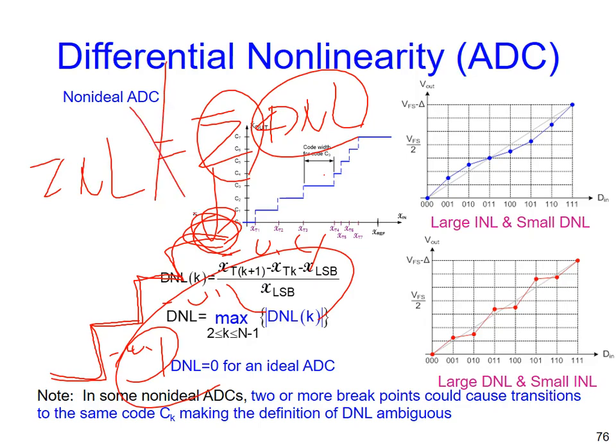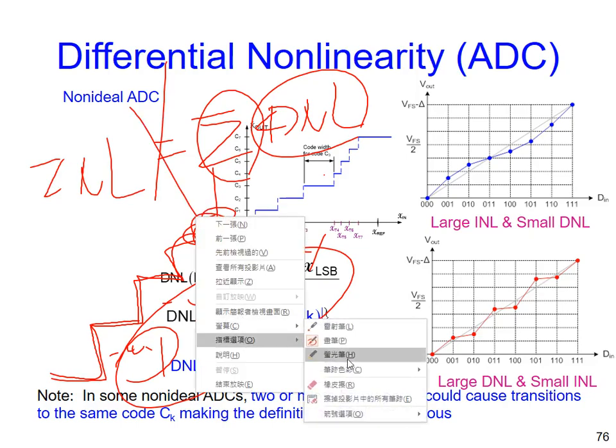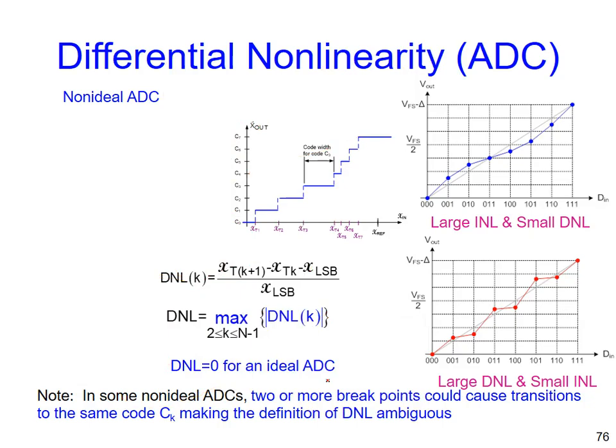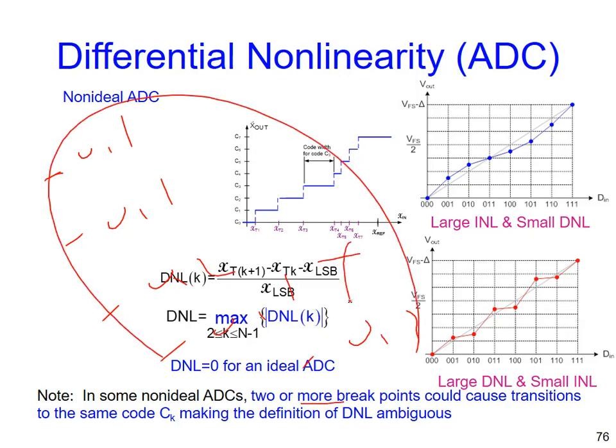Okay, so this is the relationship between INL and DNL. You can see, even if the DNL is small, for example, minus 0.1, how about next? Minus 0.1. Minus 0.2, minus 0.1, minus 0.3. But you need to sum them up. If you look back to your juniors, hey, they don't do a good job. They get very bad DNL, right? All of them need to sum up to become your INL, right?